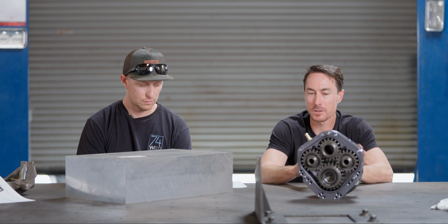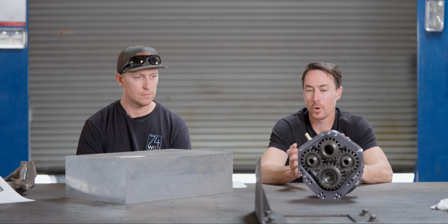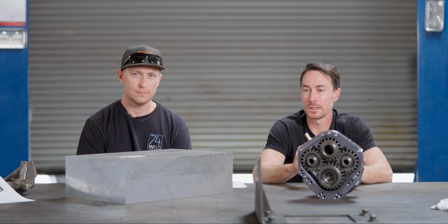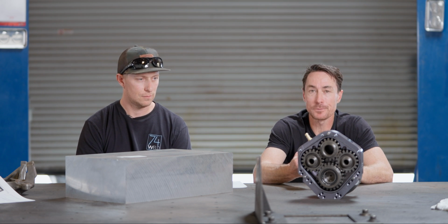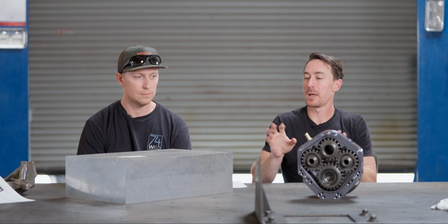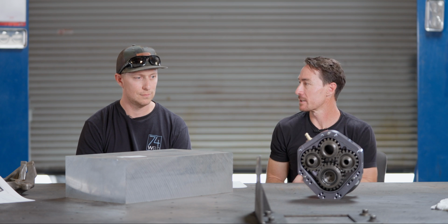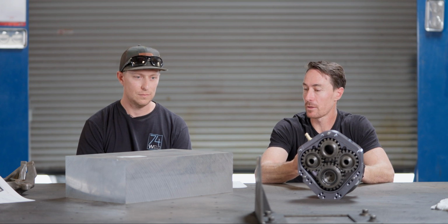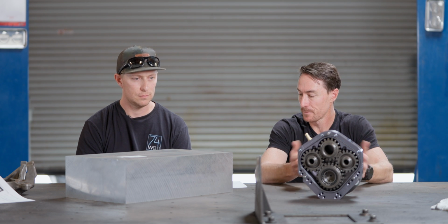It never turned out to be an issue on this stuff. We just don't have heat problems. But I guess where I'm going with this is what really matters is selecting the right material for the right application. And to make a blanket statement like 7075 is better than 6061 because it has a higher tensile and yield strength is kind of missing the point and oversimplifying something.